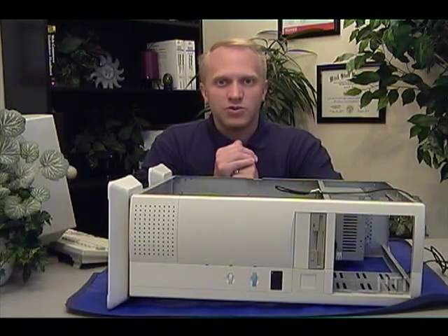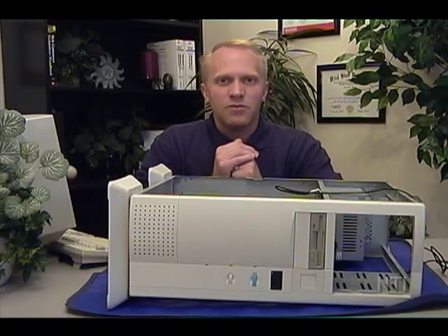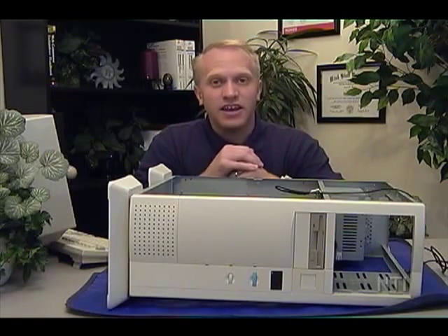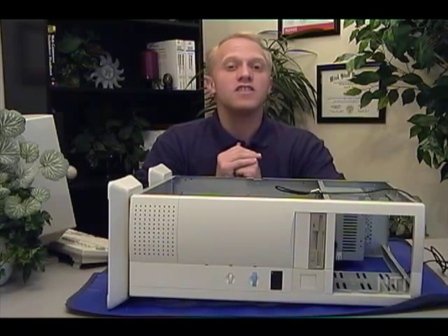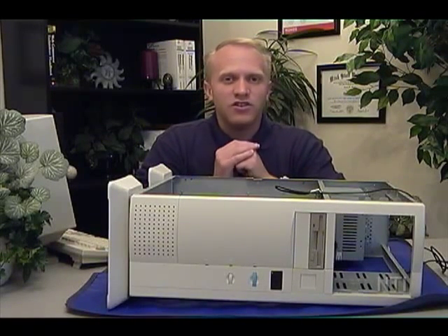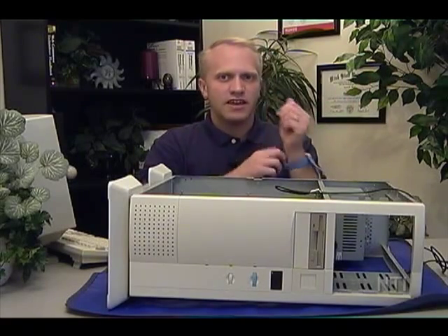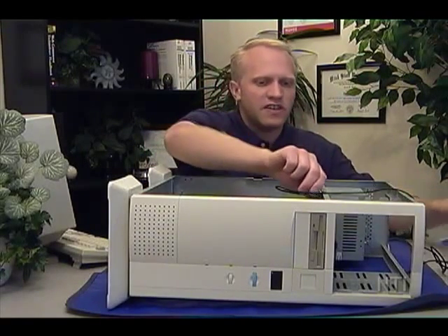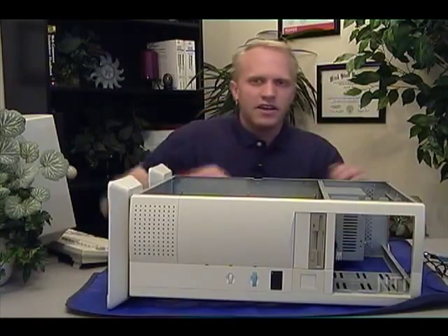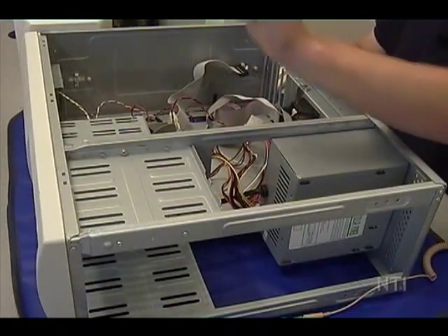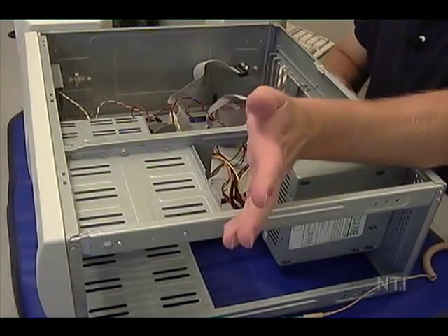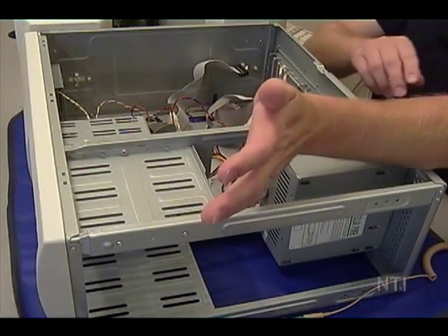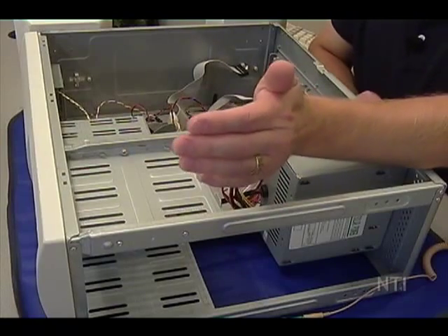Now there will also be times when you're out in the field and lo and behold you don't have a static mat to ground yourself to while you're working on a computer component. That will happen all the time, I promise you. There's a way to do it without all this fancy equipment, and that is, instead of using these clips to ground yourself to a mat, all you have to do is just maintain contact with the case at all times while you're working on it. It accomplishes the same thing that the static mat does, and that is maintain an equilibrium in the electrical potential between you and the case.